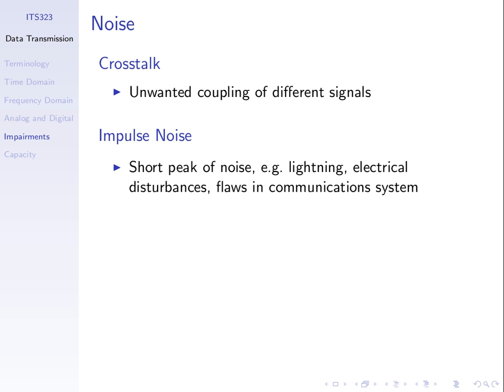Similar, crosstalk is an example. You have 2 cables. Here's one cable and you have it along the floor and a second cable next to it, very close. The signals can interfere with each other and cause what's called crosstalk noise on each other. Sometimes it happens on telephone calls, that you can hear communications or interference from another source when you're talking to someone on the telephone. Interference from other nearby sources.